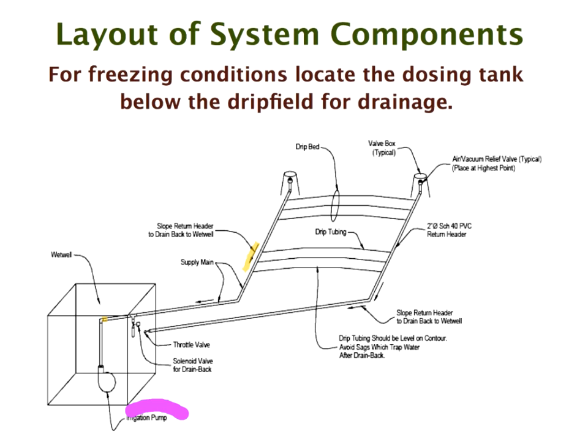Okay, I apologize, I didn't even see it the first time on this drawing. The water's meant to be going that way, pumping up. What they're showing is the drainage. What they're showing here is when you switch off, not when it's operating, but freezing conditions below the drip field. So this can drain back.